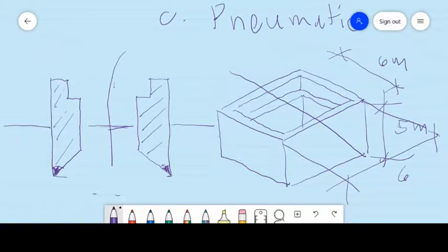Note that at this portion is the cutting shoe. This is made of a metal sheet so that during sinking, this will not break. Imagine if this caisson has no cutting shoe and is only made up of concrete. The first portion that will break during sinking would be this part. So to avoid that, cutting shoes were placed all around the perimeter of the bottom of the caisson.